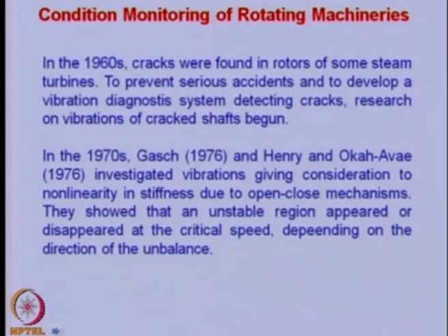So, in 1960, cracks were found in rotors of some steam turbines. To prevent serious accidents and to develop a vibration diagnostics system detecting cracks, research on vibrations of cracked shafts began. In the 1970s, Gasch in 1976, Henry and others investigated vibration, giving consideration to the nonlinearity in stiffness due to open-close mechanisms. They showed that an unstable region appeared or disappeared at the critical speed depending upon the direction of the unbalance.